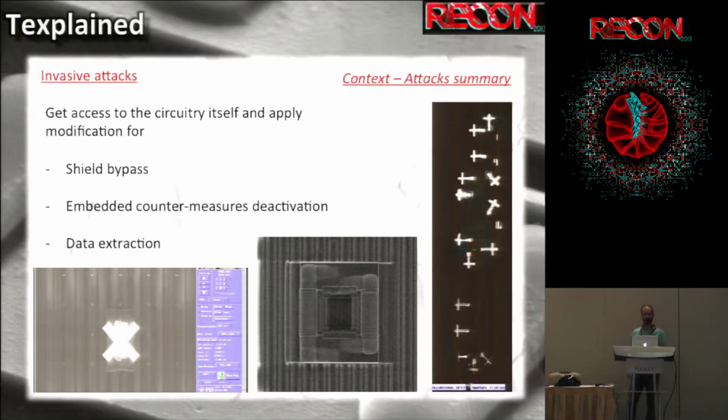On the second picture, I wanted to have some space to reach something that was below. So I had to cut the 2 lines and replace them on the side, and the chip will still work. And in the last picture, all these crosses are probe points. There are 16 pads to put needles on a bus and get the data. So this is very nice.